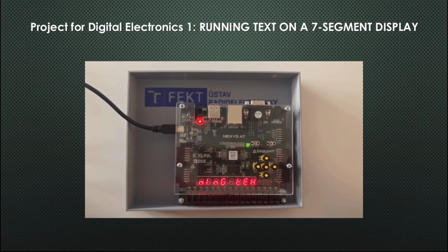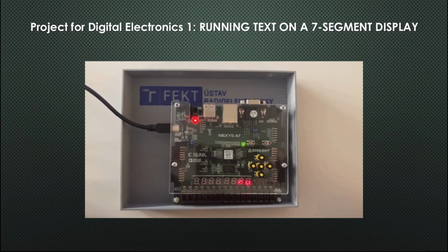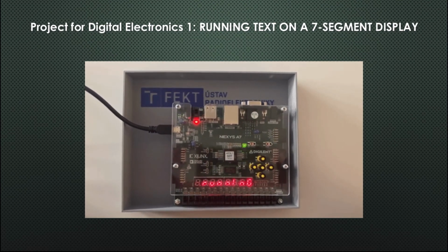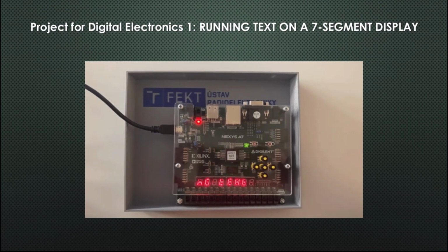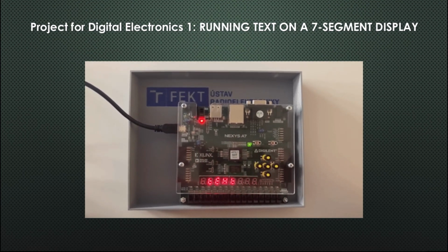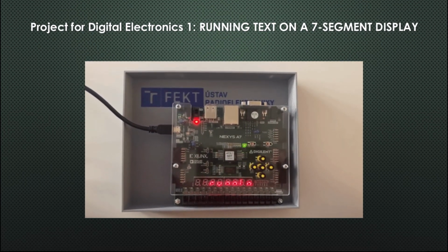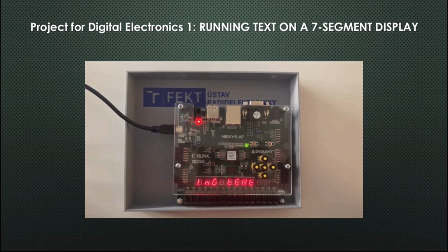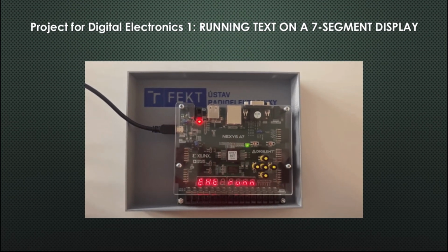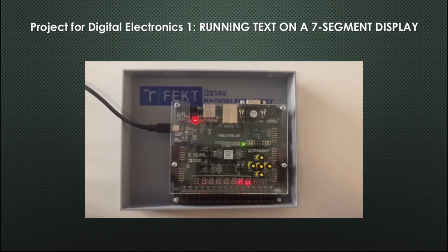To sum it all up, all of this theory was quite good and thought through by us, but on the real hardware it didn't quite work. There were some problems with loading data via serial line. In order to fix it, we have tried many things, such as flipping bit order or adjusting, even removing some modules, but nothing worked. Since the main topic of our project was just a basic running text on 7-segment display, we decided to fill the data register with static data. However, for proper function, we only need a serial data stream, meaning the module could be easily replaced with a debugged module from another application.